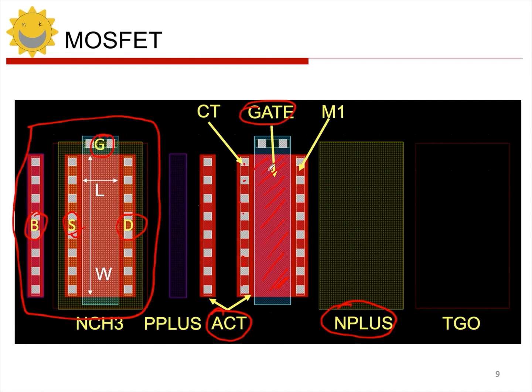At the same time, there's another layer. What's it called? It's TGO, as we just discussed, right? Triple gate oxide. So what does having TGO mean? It means it's a MOSFET formed after oxidation, specifically a high voltage device, right? So with that, our source drain region is all set up. Now let's take a look at the gate. The gate also needs to be connected out using contacts and metal, and this is how the gate looks.